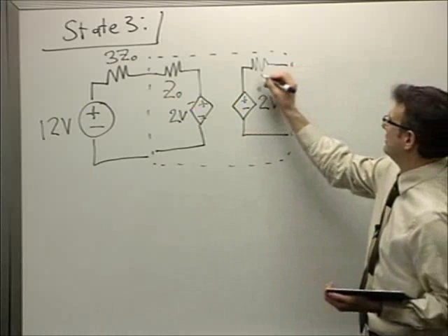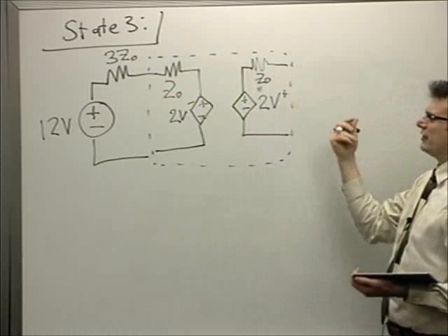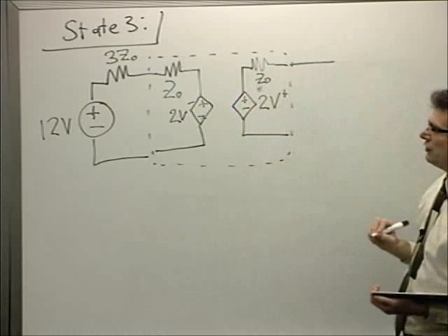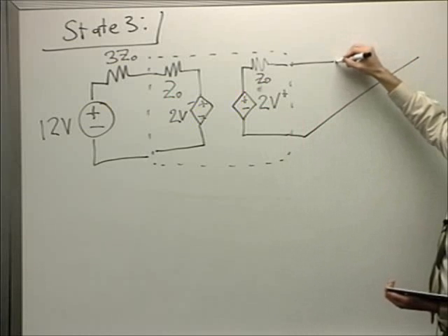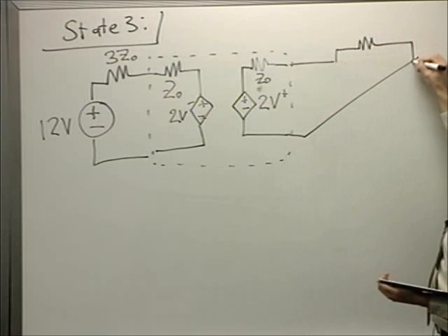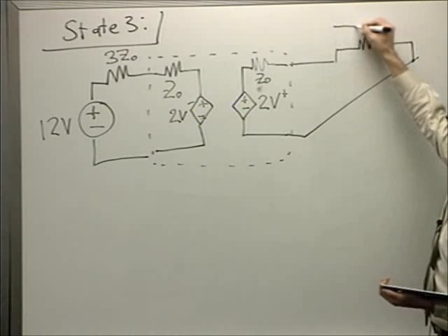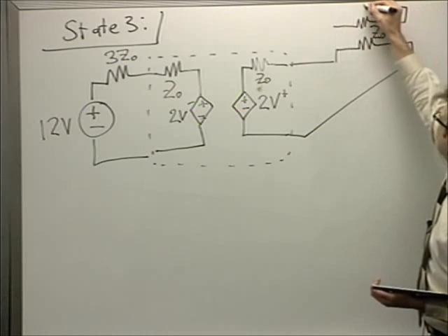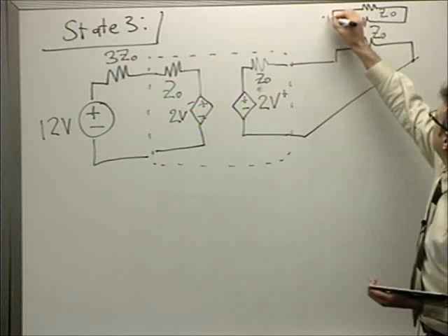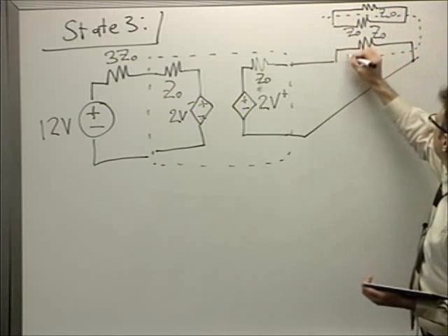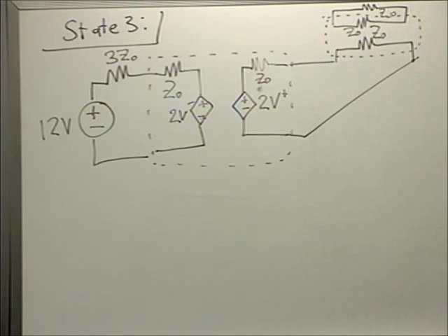And then I have another dependent source with Z0 impedance that's 2V plus on the other side of the line. That's connected through a closed switch B, a capacitor, which looks like a short circuit at this moment, and then it's connected to a dead line equivalent model for that second transmission line. Z0 in parallel with Z0. I don't even know why I drew that part of the circuit. That's not doing anything.